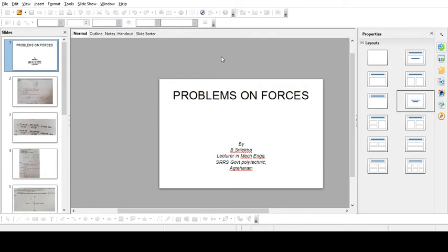Now if I take this triangle ABC, out of this, theta is the angle between this string and the horizontal. Now cos theta is adjacent side by hypotenuse, nothing but BC by AC. BC we already know, that is the radius 200, and AC is the length of this string. So 200 by 400 is 0.5, that is 1 by 2. Cos theta is equal to 1 by 2, then theta would be 60 degrees.